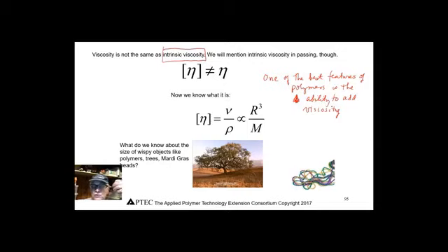From a physical point of view, what this intrinsic viscosity is, it's sort of like the hydrodynamic radius, the hydrodynamic control. Okay, so it's what volume of liquid is controlled by the polymer per unit mass. And it's enormous for polymers. It's just enormous. It's not like anything else you can think of.